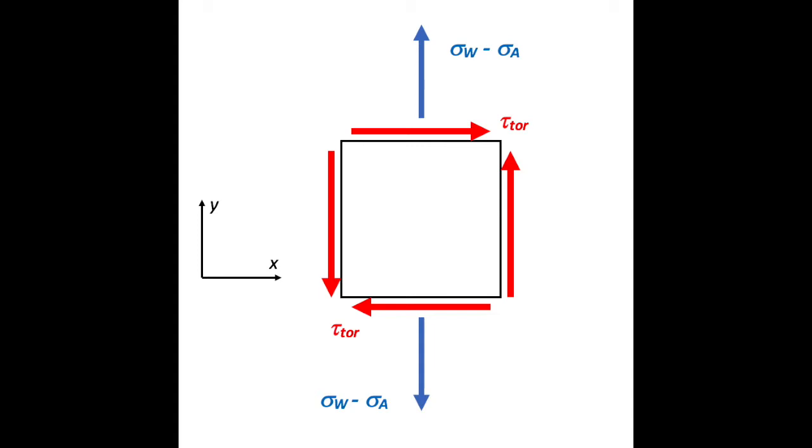Lastly, to maintain moment equilibrium on the element, there must be internal shear stresses on the right and left sides to counter the couple moment generated by the torsional loading. Note that the transverse shear stress is 0 at this point.